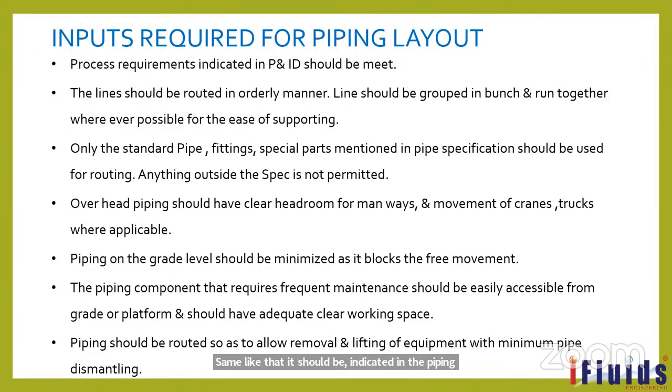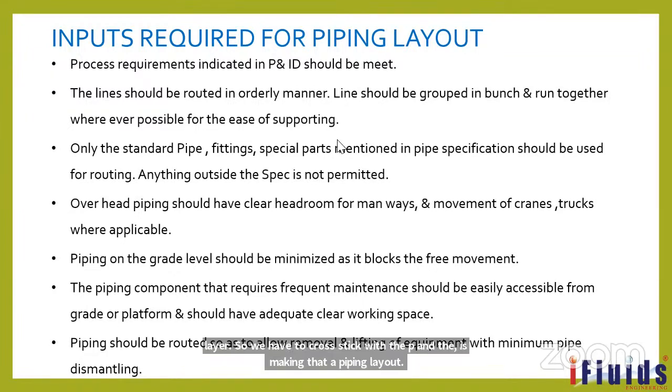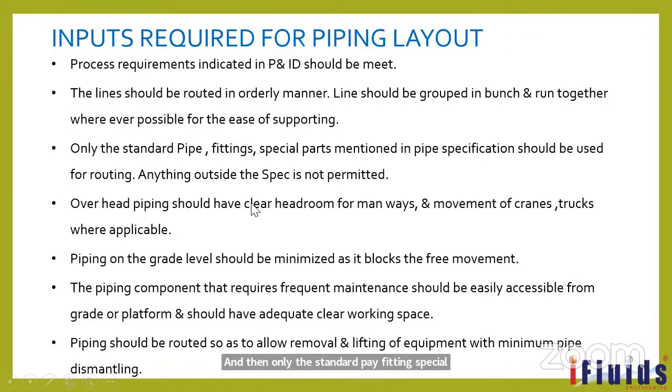And then only the standard pipe fitting special part mentioned in the piping specification should be used for routing. Overhead piping should have clear headroom for manways and movement of cranes, trucks where applicable. Okay, these are all normal things.